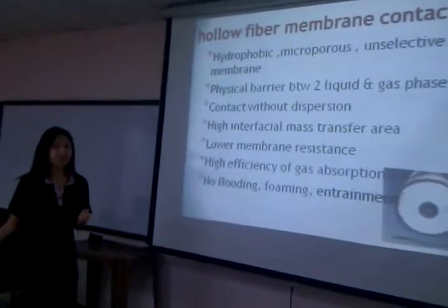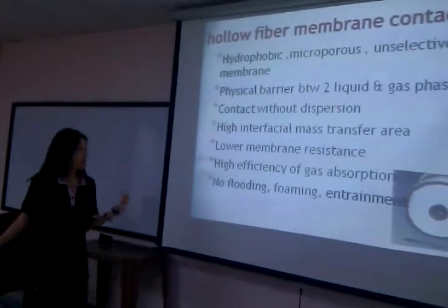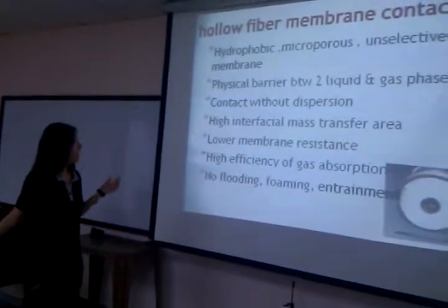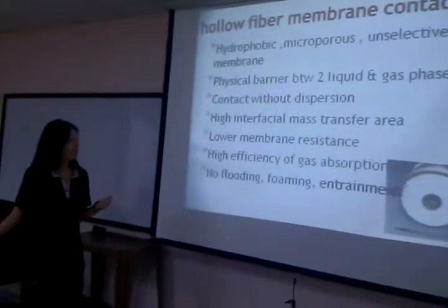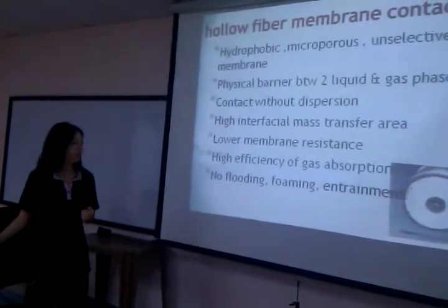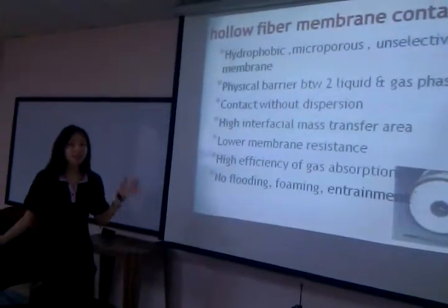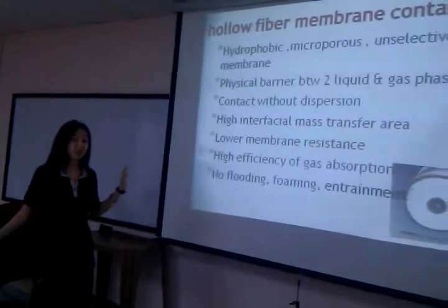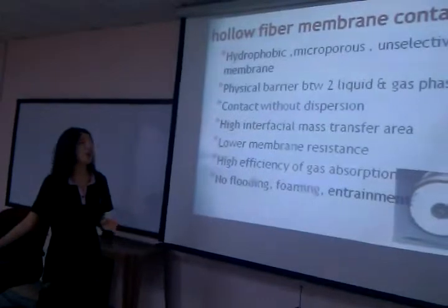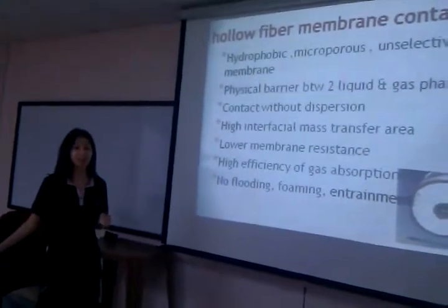Hollow fiber membrane contactor also provides many advantages over the conventional devices. For example, higher interfacial mass transfer area, lower membrane resistance, higher efficiency of gas absorption, and the main difference from the conventional devices is that no flooding, foaming, and entrapment occur in hollow fiber membrane contactor.